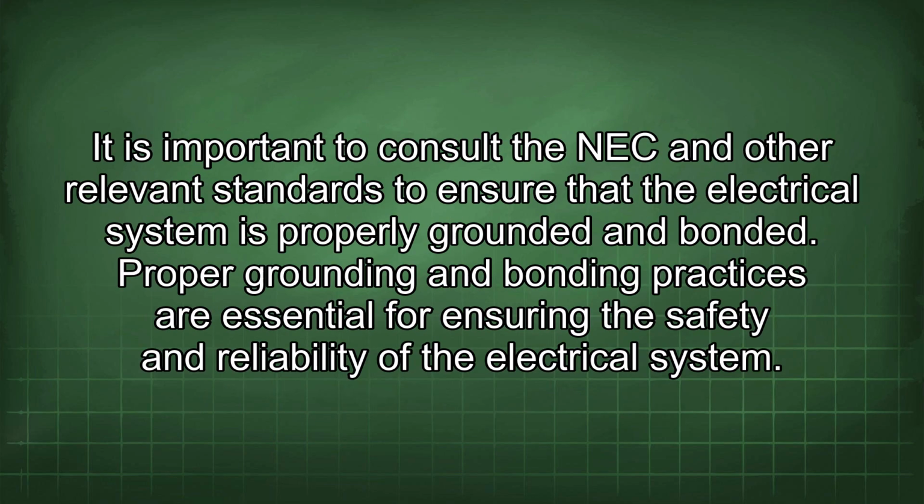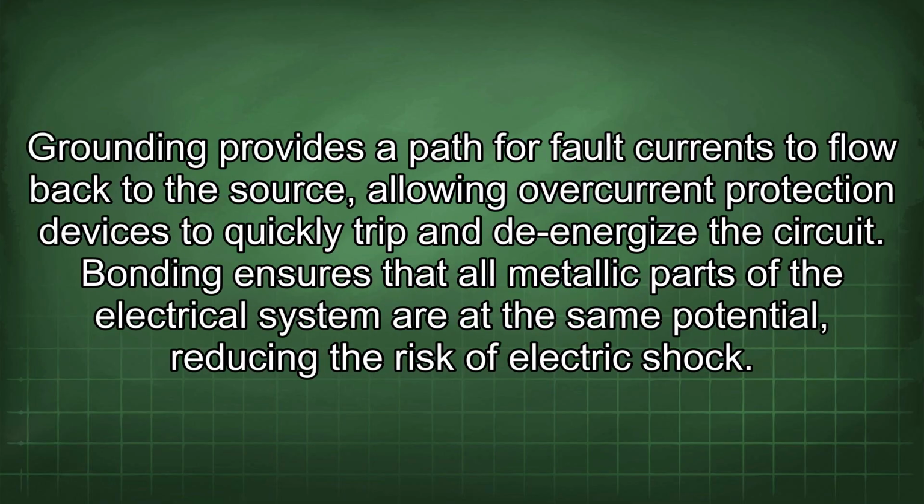It is important to consult the NEC and other relevant standards to ensure that the electrical system is properly grounded and bonded. Proper grounding and bonding practices are essential for ensuring the safety and reliability of the electrical system. Grounding provides a path for fault currents to flow back to the source, allowing overcurrent protection devices to quickly trip and de-energize the circuit.